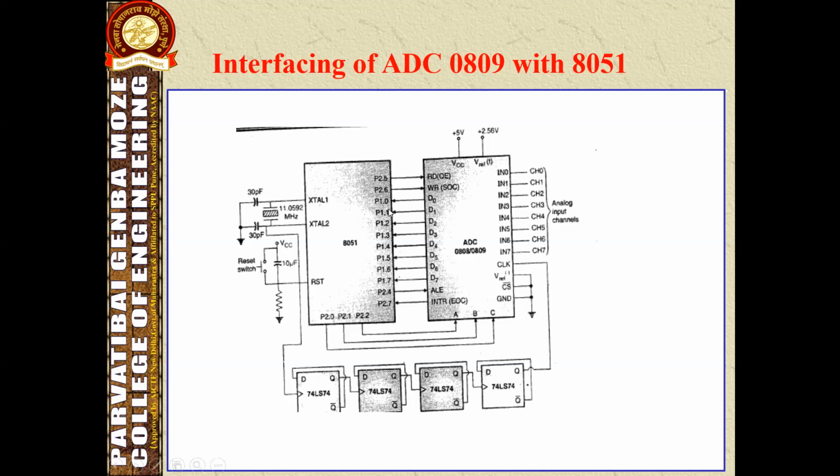Here port 2.0, port 2.1 and port 2.2, these pins are connected to the ABC address pins of the analog to digital converter to select the appropriate input.